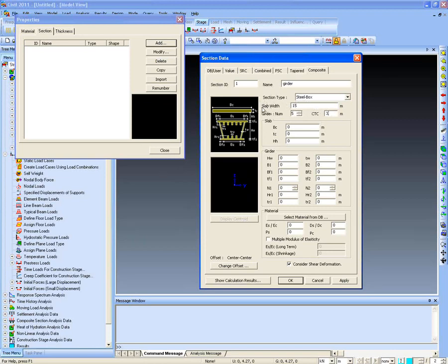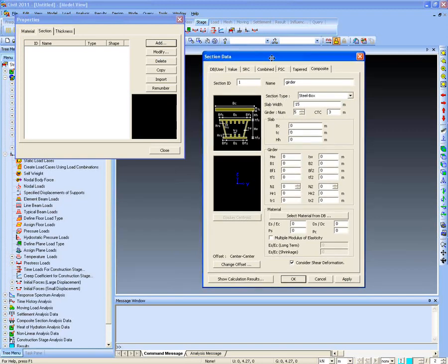Here I would like to tell you that we have to enter the total slab width for the calculation of the IZZ, because in real practice the deck will be continuous, but when we model the same deck in MIDAS Civil, it will be modeled along with the beam. So for calculating the IZZ, the program asks the user to enter the entire slab width, and then the IZZ for the entire slab width is calculated and divided among the girders.